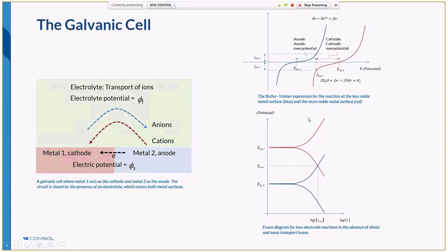If you're unsure of the data required to get started with the simulation, the material library within COMSOL contains a number of predefined materials with the electrochemical kinetics taken from scientific literature. This feature was added in our most recent version 5.6 and contains electrochemical data for steels and alloys of zinc, copper, aluminium, nickel, magnesium, and titanium. Many of these materials have these properties defined at different temperatures and different salinities, so it can provide a good starting point for your simulated material properties.